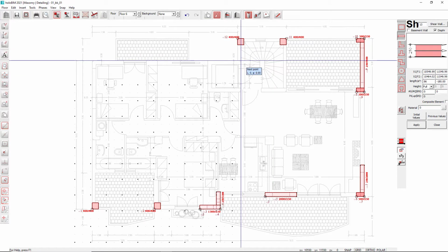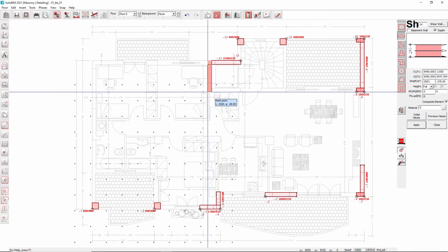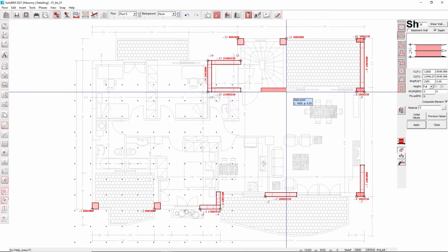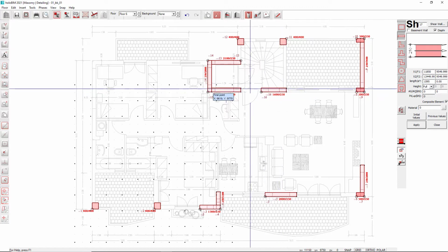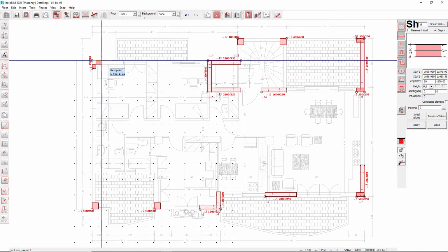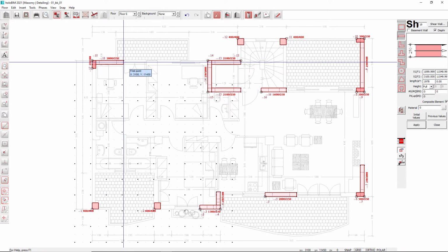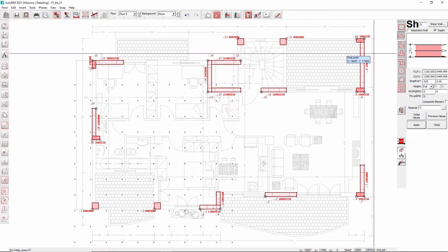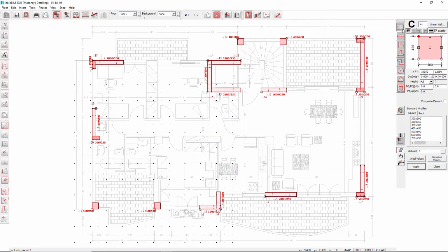The elevator can be either described by using the available column type, or by combining shear walls in order to create the composite section of the elevator. These shear walls should then be unified into a single structural element. The software offers a wide variety of column types, and the user can even combine different types in order to create the composite column sections necessary for a specific project.